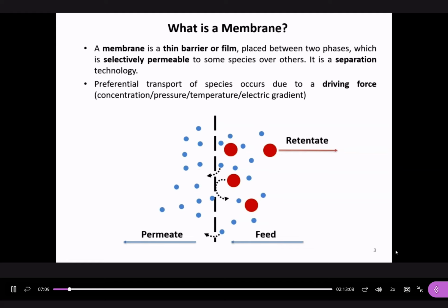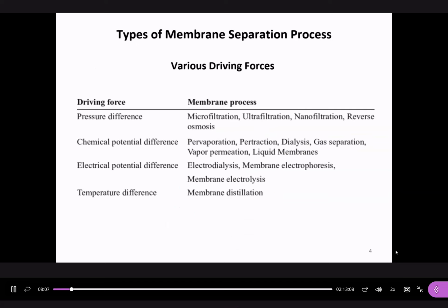This is a very simple scheme. You see that there are some pores, and we have the solutes and the water molecules. This is a very ideal scenario, with 100% rejection, or 100% retention of the solute. But in reality, we cannot have such perfect pores. They have a distribution, and in many cases you cannot achieve 100% retention. Probably 99%, 95%, etc.